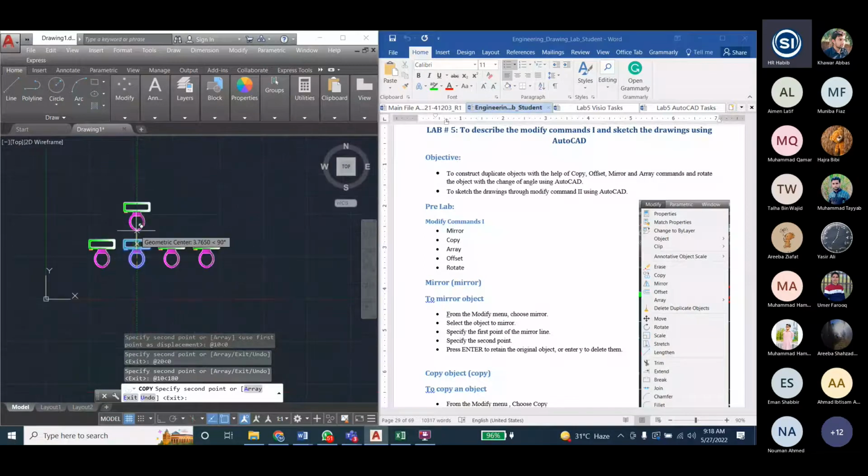If the green line is appearing, it will help you apply exactly, but the distance between two figures may be different. This green dotted line will help you place it exactly vertical. Otherwise, you can also switch on or activate ortho mode.